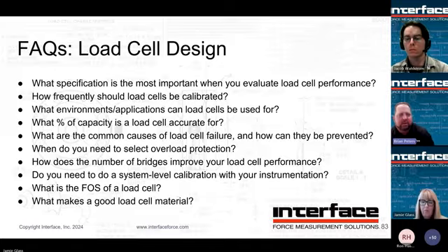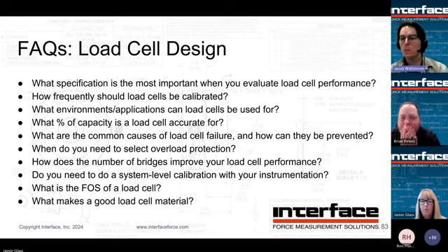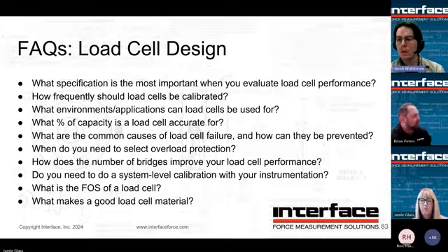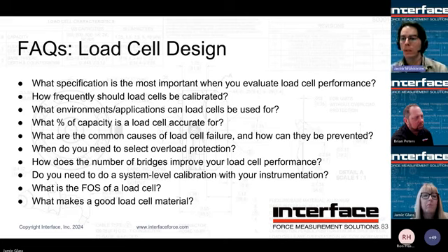All right, what's the FOS of a load cell, Jacob? Yeah, factor of safety. That's going to be printed on our spec sheets. It's going to be the ultimate load. It's normally, I think for LPs, 300%. And that's when the yield strength comes into play of the flexure of the spring. And if factor of safety is something that your application needs to hit a certain target, definitely reach out to our applications engineers. And we might want to derate a cell to get a little bit more overhead. That's relatively common.